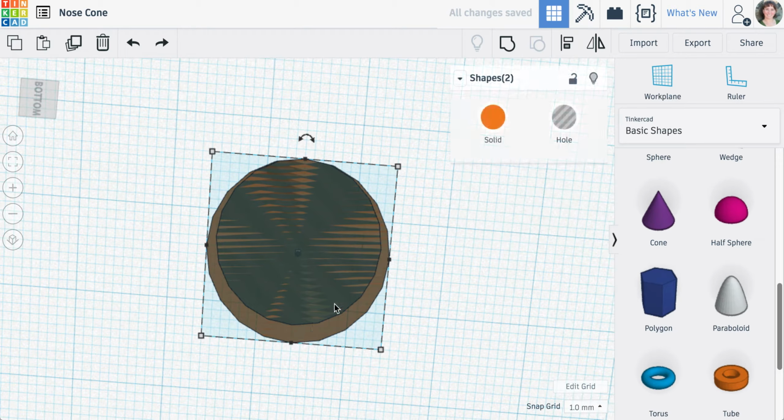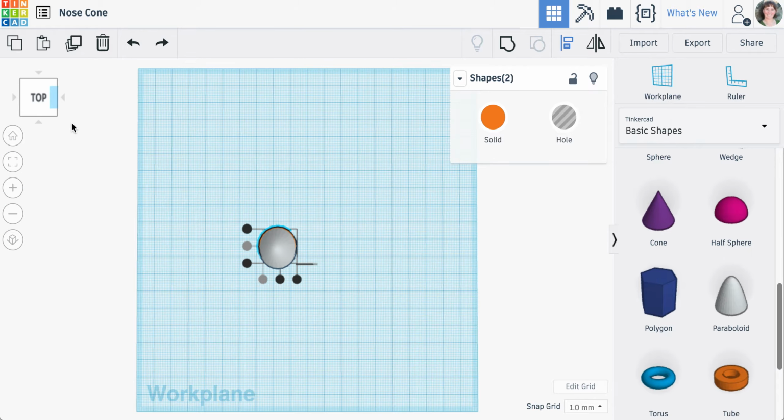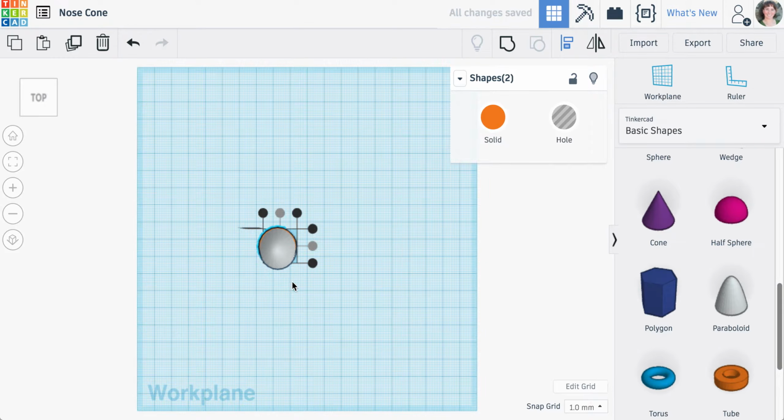So if I click on the two shapes again, and then click on the Align tool, this might be easier done from the bottom in this case, but you can also look at it from above, and the same sort of thing happens. But basically you wind up clicking on the arrows for the middle on each side. Now that I can't click on them, that tells me that the two shapes, the hole and the solid cylinder that I've selected, are aligned in the center for each one.